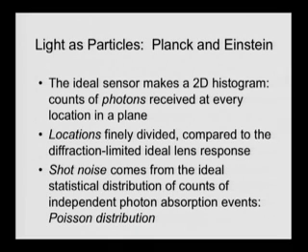Anytime light goes into the silicon crystal, a photon gets kicked up into a state where you can collect it, measure it, count it. And if you can count it with a fine enough resolution to say exactly where it is, not just how many, but how many in what location, then you get a perfect ideal image. As long as that location is split up finely enough compared to the wave diffraction effects, then there's essentially no loss of information. That's how we're going to define an ideal sensor. The ideal sensor tells you where every photon came in with a resolution finer than the diffraction of your imaging system. These systems have noise.